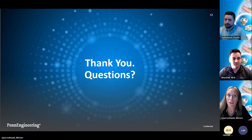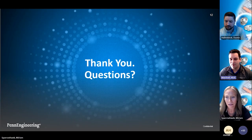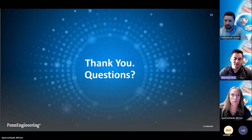Great. Nick, there's been a question about the current rating limits for each contact point. Is that too specific? If we're getting too specific, maybe we'll reach out separately. Yeah, we can follow up with testing data. It's very dependent on the size of the contact point we're talking about. Our standard eConnect bushing in an M6 size carries about 400 amps of current with a sub 20 degree Celsius temperature rise. As we scale that up, that current rating increases. As we scale it down, it will decrease.